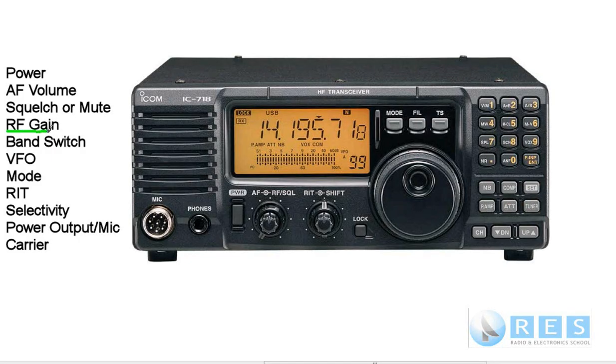The RF gain, very important control. The RF gain is the control that changes the sensitivity of the receiver, not the volume of the receiver. The AF volume does that. The RF gain increases the sensitivity of your receiver, making it possible for you to receive weaker signals.